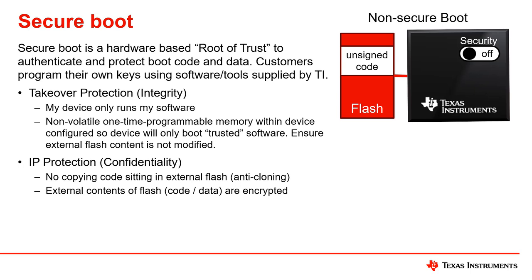As we can see on the right-hand side of the screen, in a non-secure system, really the system is going to run any code that is placed in flash at the right address for when the processor starts up. And this is great for design and development, but obviously for a system that has risks and needs to implement security, this is not going to be good, because anyone that knows how to put code into that flash at that address is going to be able to get the system to run code that they might want it to run. And that's a non-secure system.